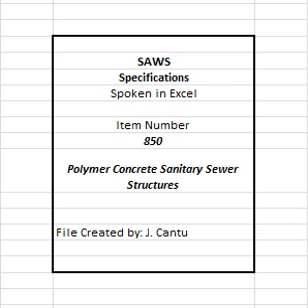B. Approved manufacturers are listed in the SAWS APL and have previously completed required inflow leakage shop testing. C. The nominal cover diameter shall be 32 inches, with a 30-inch clear opening, as required by TCEQ. D. Vented structure covers will be specified by the engineer. 24. Throat/grade rings shall be made of HDPE and have a maximum thickness of 2 inches, and the uppermost adjustment ring or flat top, see approved APL. A. No concrete throat/grade rings shall be used. B. The internal diameter shall match that of the ring and cover opening.